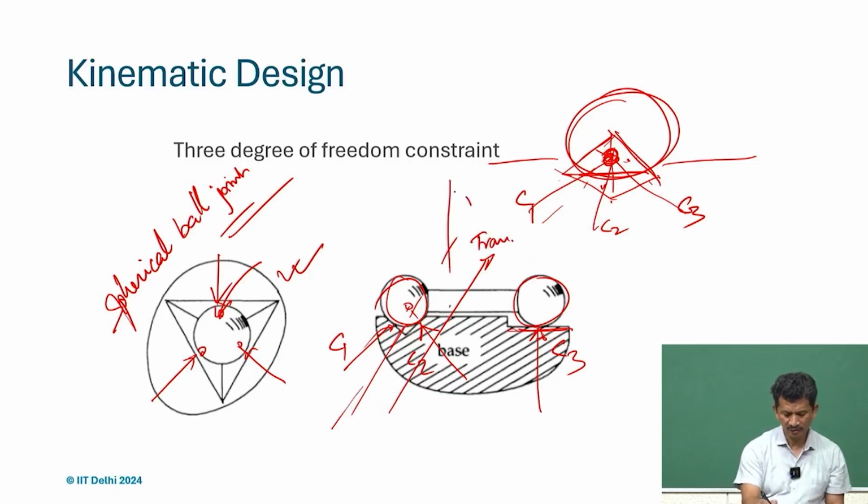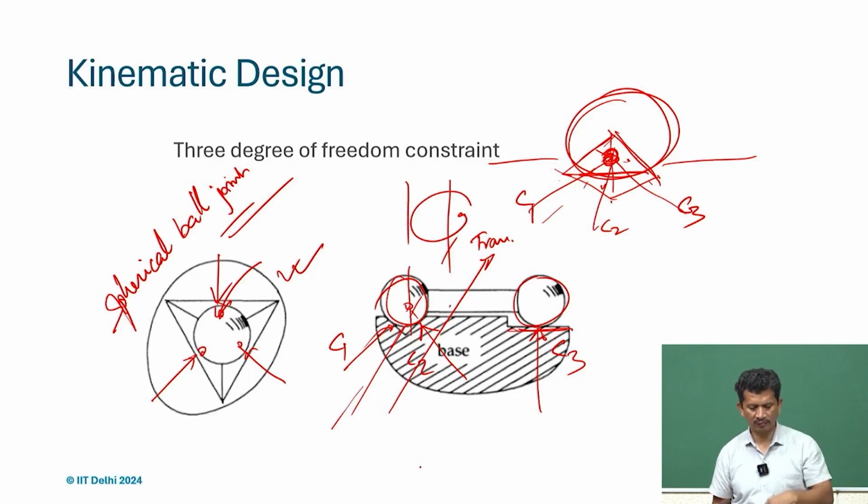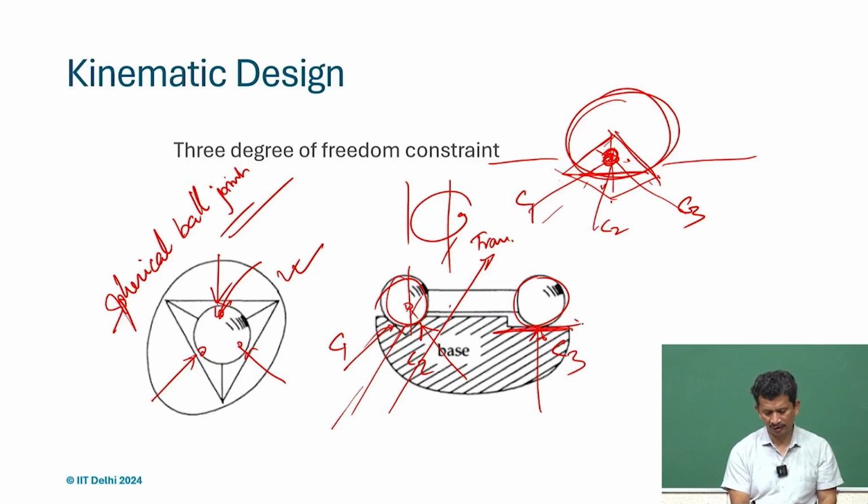Another is this rotation. If we just try to rotate, the orientation of the bar will change, and since the flat does not oppose any constraint in this direction, it can slide and can reorient. Therefore, it is also possible to have Z rotation. So, we will have that in and out motion, and we can have that Z rotation as well. So, again 2 DOF here.